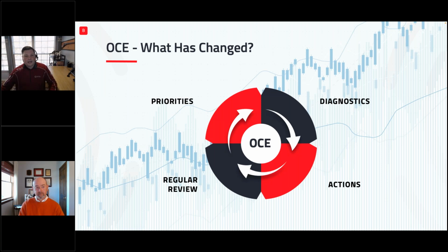Prioritizing actions is what keeps us sane, because if we were to look at the OCE across 2,000 loops in a plant, you may have, let's be honest, 300 red lights blinking at you. You can't fix 300, so how do you prioritize? Well, you look at importance, the cost of that loop, the value of that particular asset, and you roll that in to help you prioritize.